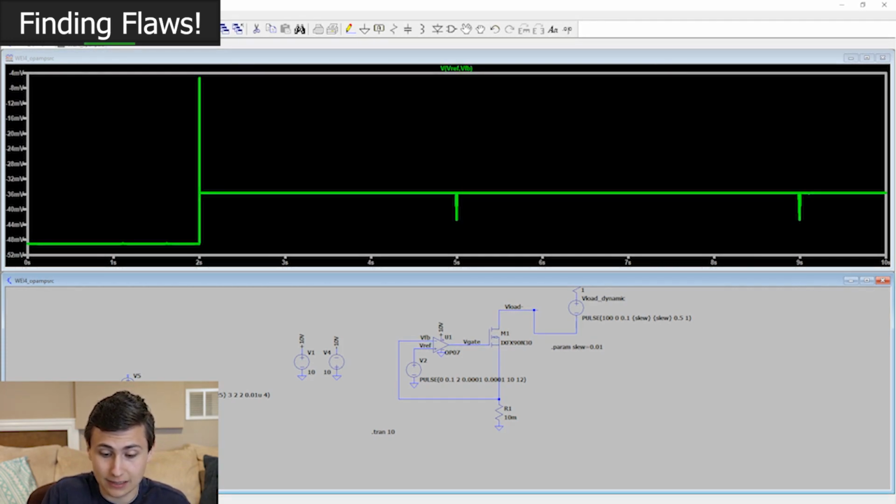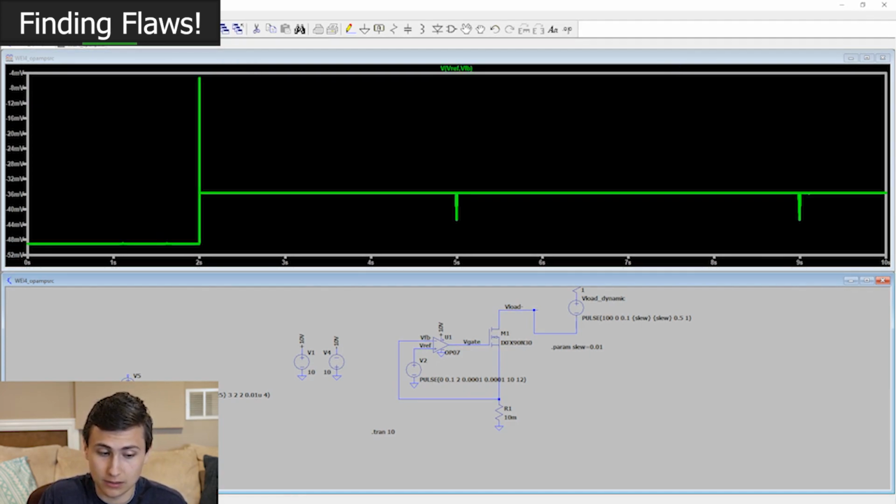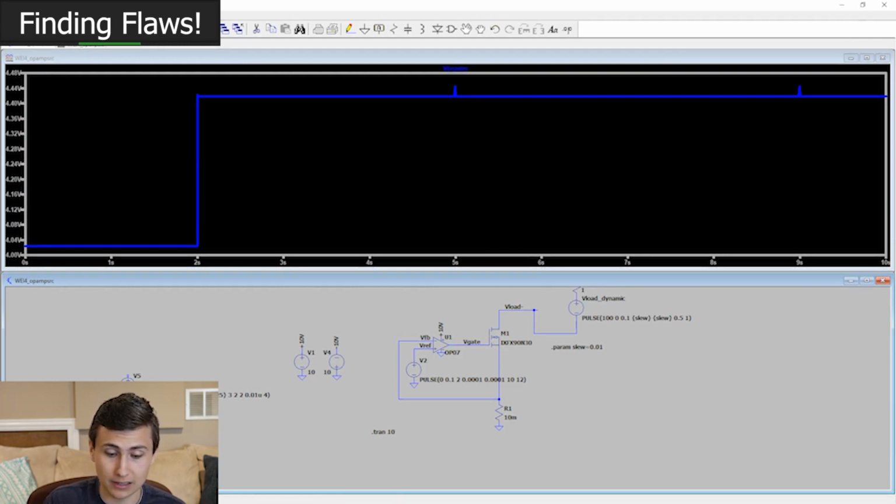And in this case, that difference that makes 4 volts come out is 36 millivolts. And that's the steady state error that we're seeing. That's how much input we need to bias this MOSFET at this voltage. It's not really how I would want to see this thing work, and that's just dependent on the gain of that op-amp.